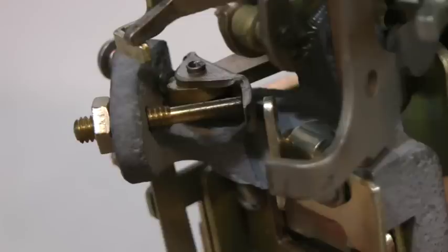For clarity, I have added a clip here using my spare parts switch, showing the mechanical motions of the rotary pawl. It is the tip of the pawl that engages the ratchet teeth. The rotation of the wipers by one step brings them to rest on the first terminal of the 10th bank level.